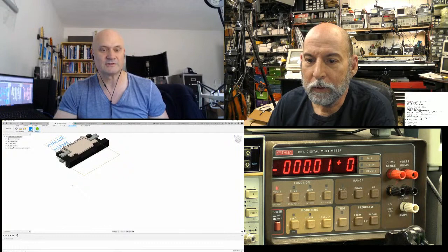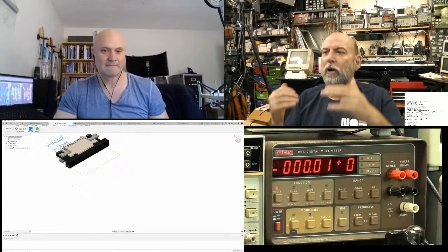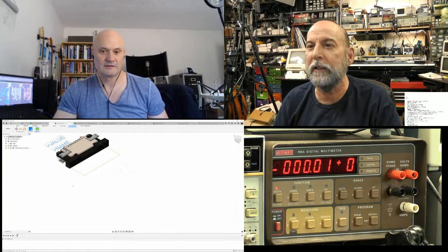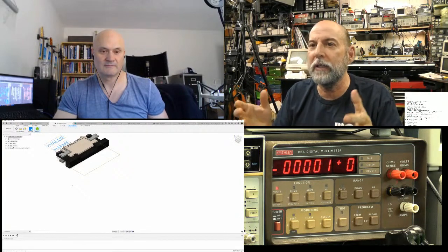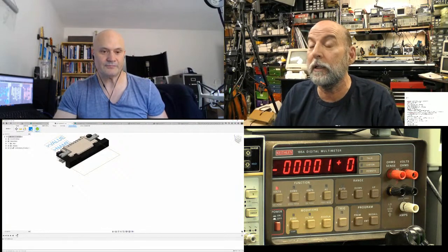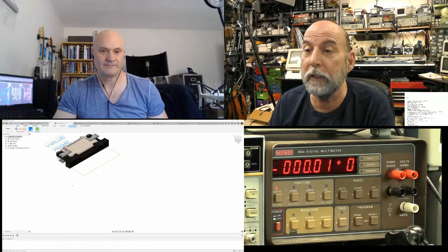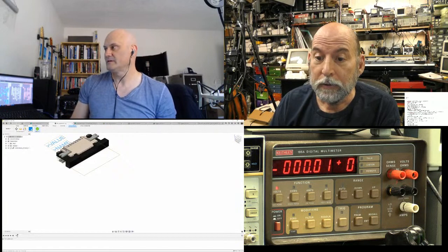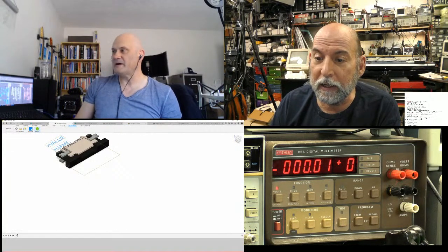Pinouts can be wrong too. And the layers don't always translate between the different manufacturers. So the first thing you check is, did it put it on the right layer, or did a piece of something get lost in the layer transition? Right. So now anyway, I'm lazy about all that.